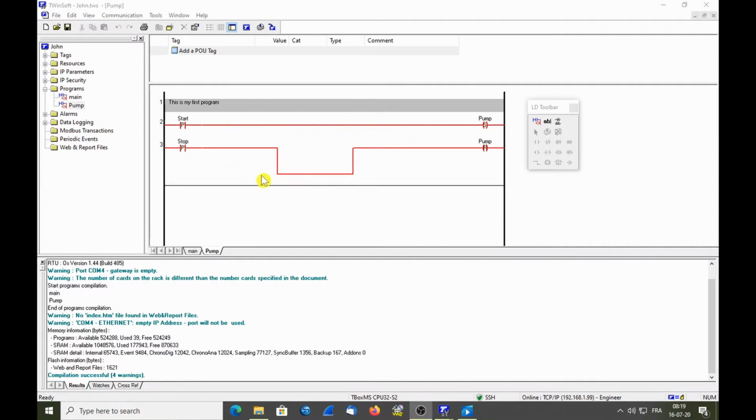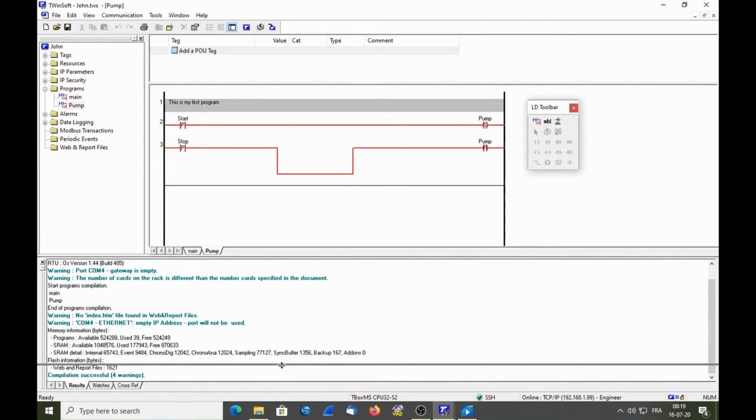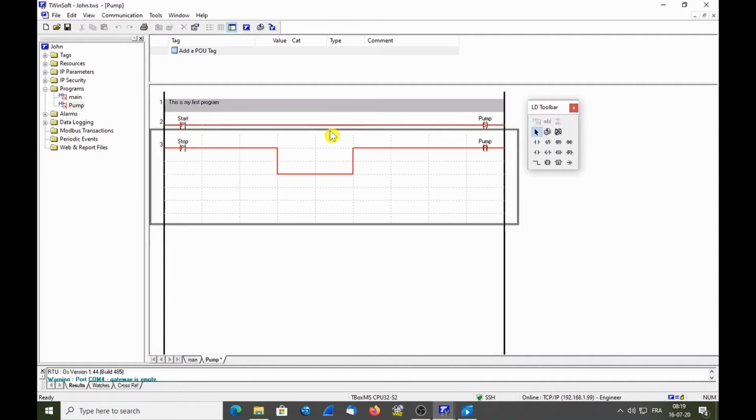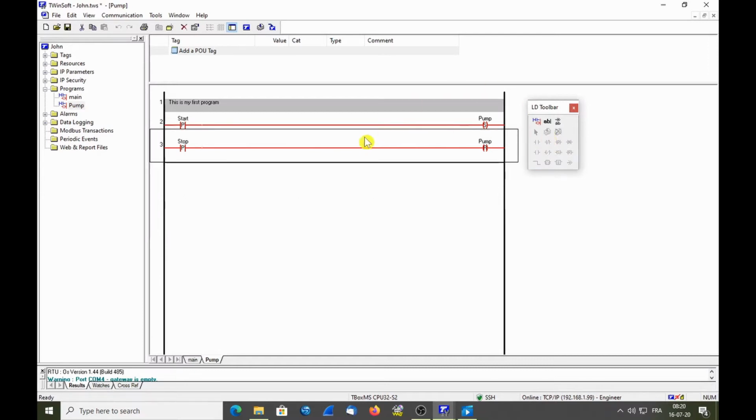So let's adapt this code in order to take into account the temperature of the pump and the level in the water tower. First I will reduce this window and I will update the lines here. So if you want to edit a line, you just double click in the line, you enter back into edition, and then you see when you move you select object, and you can just delete object, delete object, delete object, and I will draw a new line. OK, and I press accept changes. I will edit the lines to add an automatic mode and also an emergency stop.